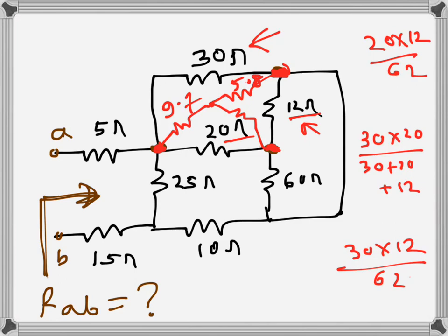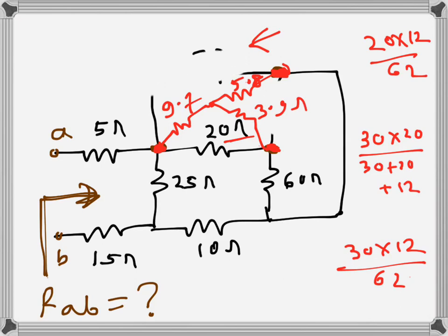Maybe I will start erasing, because I want to erase the delta resistances finally. Let's erase that one, and that's 3.9 ohms here. And I want to erase the other deltas. This one is gone now, this is gone, this is gone. Sorry. So that's there, and then we have that. So that's 5.8. So that's what we have now.